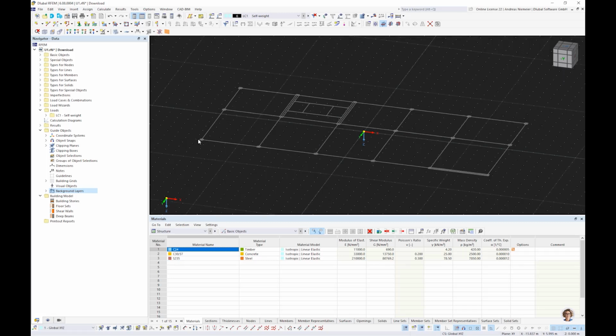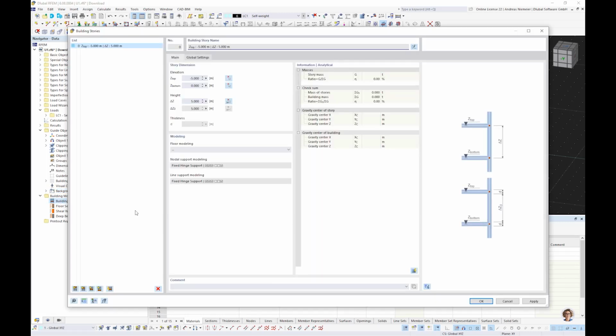Now this is at the moment no building or something; it's only the limits of it. So we start now with the building model and specify the stories. Let's say we have a 2-story building. The first story has a height of 5 meters. The second has maybe a height of 3.2 meters. My target is to use different heights. Why, you will directly see.